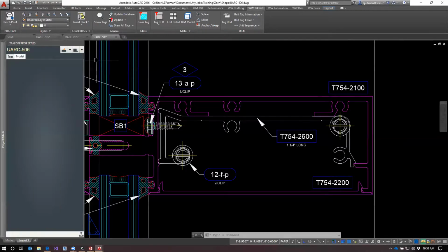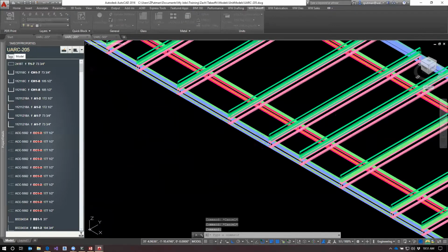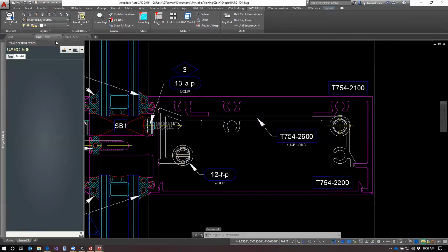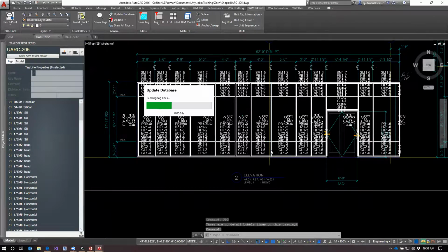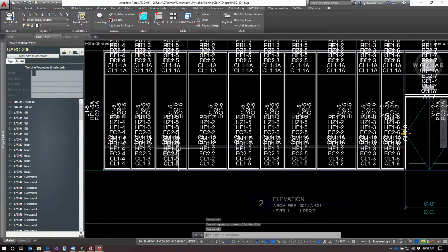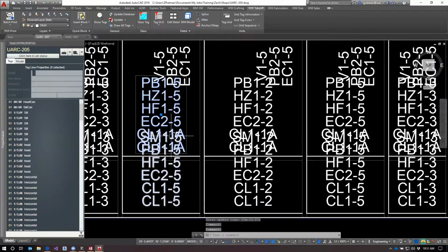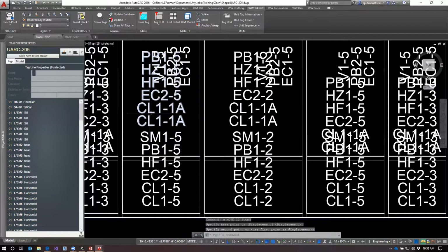So I hit apply. Again, I changed my data, so I need to close my BIM model and go back here. I've changed my data, so I need to UPD. It should recalculate. All of these clips should all be the same, at least on the horizontals, not these sill ones. But all of these all change to CL1-1A. No matter how long the tagline is, it's hard to see, but let me slide these up a bit. The CL is the shear block clip. So they're all CL1-1A. Even though this tagline is shorter than this one, they all end up at 1.25 inches long.